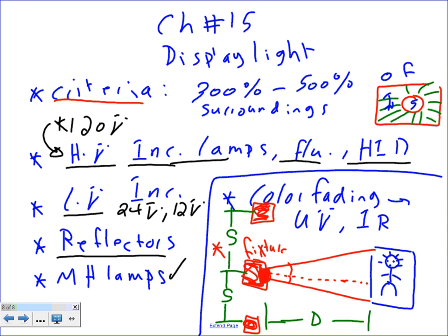What I'm looking at, Phil, is the first lamp, right? Q45 PAR 38 fluorescent. Okay, the first thing you can get about it, can you guys see the rated life for these fixtures? It's an incandescent lamp, so this is tungsten, so it's 2000 hours. The second one is beam spread. Can you guys see the beam spread that says 28 by 28?